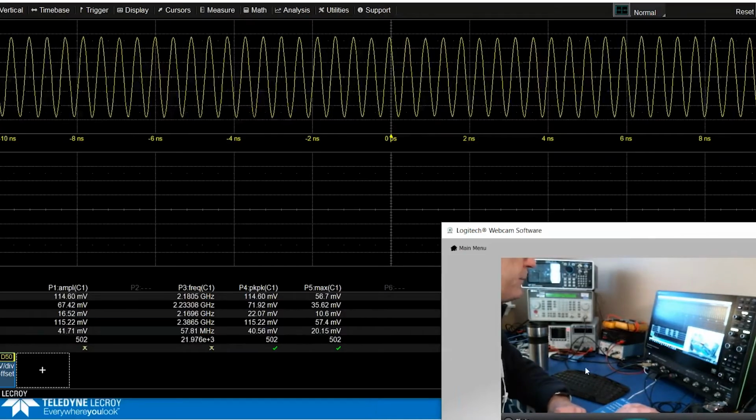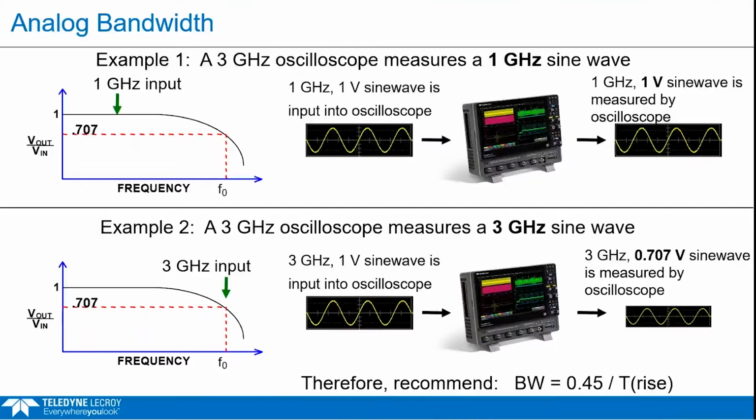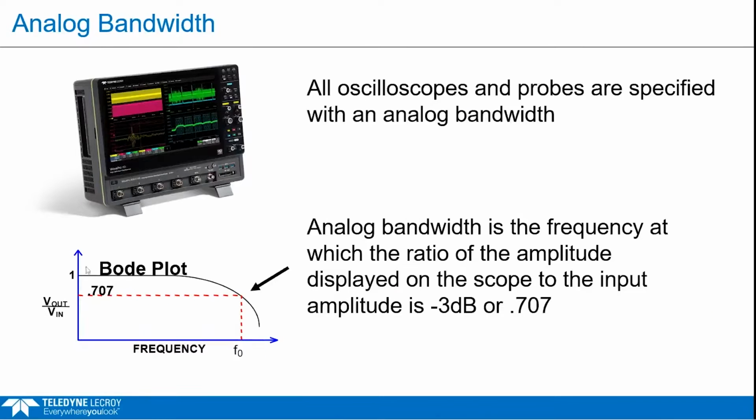Okay, and so if we go back to the slide here, I like just using this one, it's clear here. So we could see that at 2 gig, when we were specified, the scope actually gave us higher voltage, so it actually rolled off further out, which was nice. And then it did out here at 2.1, 2.2 gigahertz signal. The amplitude really started falling off, and you could see it till it was very small on the signal. And that's what scopes do.